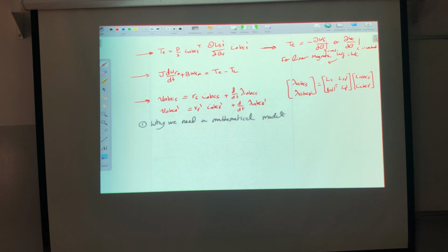We are neglecting, for example, the coulomb friction. We are neglecting the dependency of the resistance on temperature. You know that if there's a current flowing in a conductor, it will generate heat, I squared R. So in the end of the day, this resistance will change slightly due to the aging. Simply, we are going to the nameplate, and we are taking the information from the nameplate.